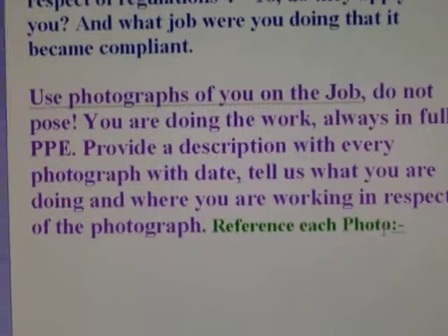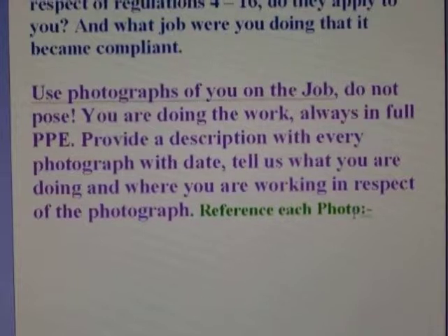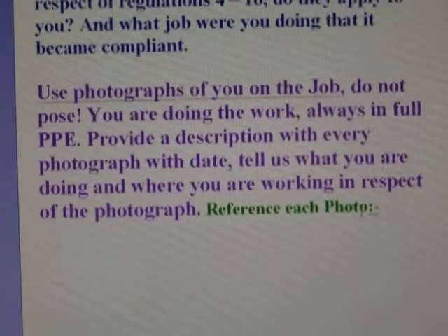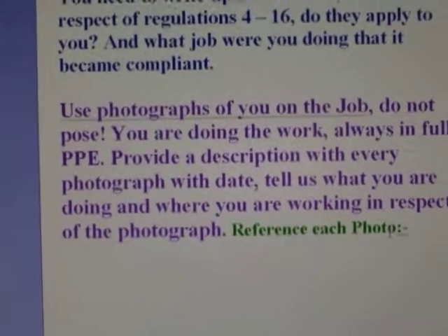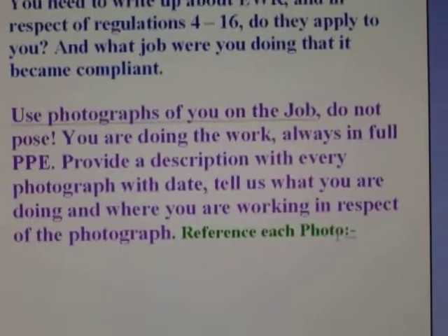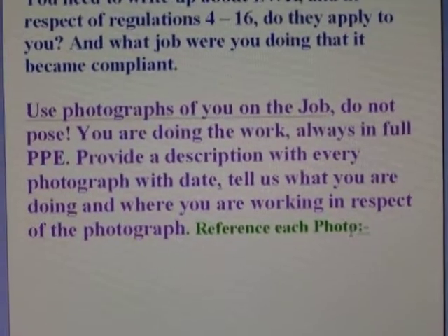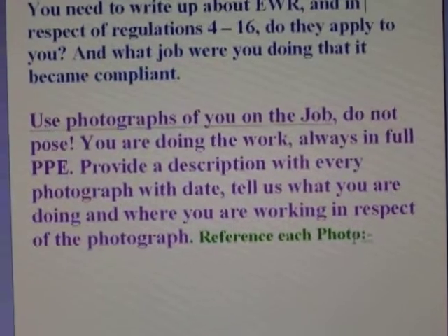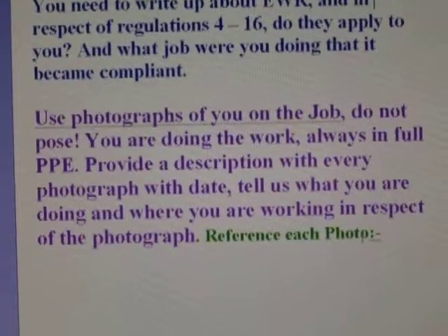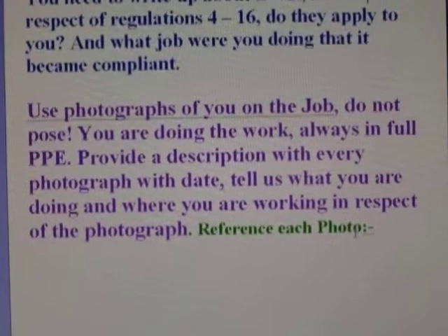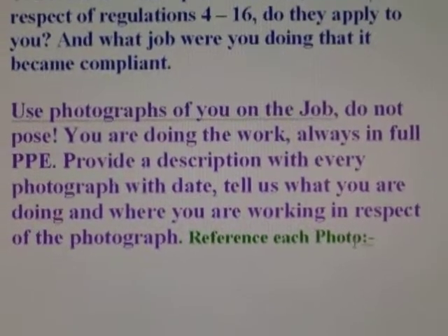What you then need to do is apply it in regards to the job you're on and where you have used it. If you take, for instance, earthing, you would do earthing in any electrical circuit. You need to earth bond, connect relevant earths in your switches, socket outlets, or in any main circuit. If you're installing trunking or conduit, you may still need to install an earth as well. So be aware of those. All this is asking you to do is bear in mind and link the work you're doing to those regulations.